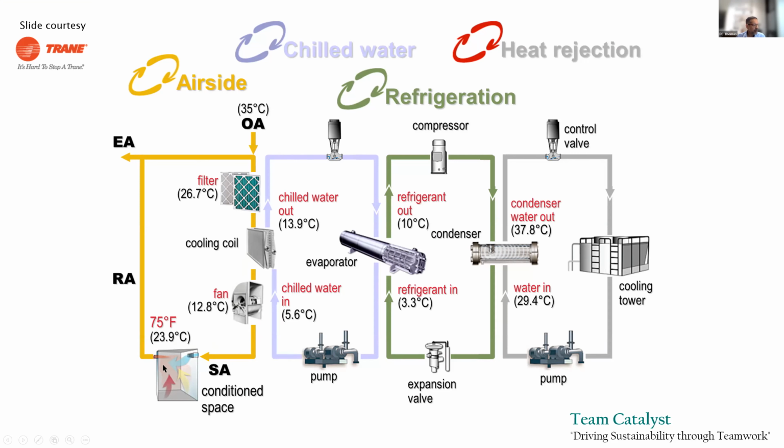This is cold air being delivered to the room, made by passing air across a coil, which is made cold by chilled water generated by a chiller. The refrigerant is contained in the chiller, sealed in hermetically sealed vessels. The condenser, compressor, evaporator and expansion valve all sit inside the chiller object.